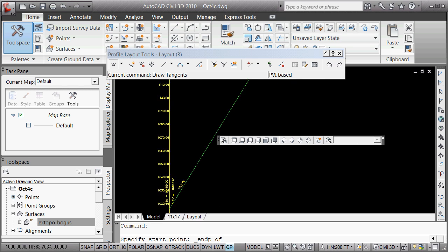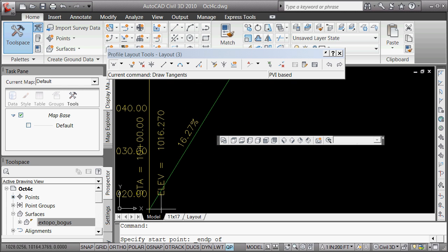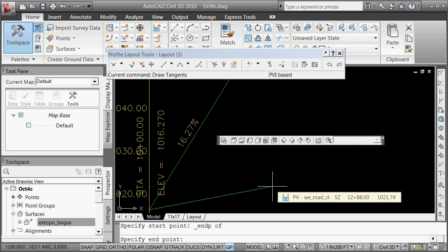So you're using a visual check. I wrote down 1050. I obviously wanted 1250, so I'm not going to use the at, right? Because we're not doing relative in this case. Though you're more likely to be using relative commands, changes in y and x, with the changes in y being 10 times the other way around, because you're actually thinking about designing when you're doing profiles between some maximum and minimum grades.